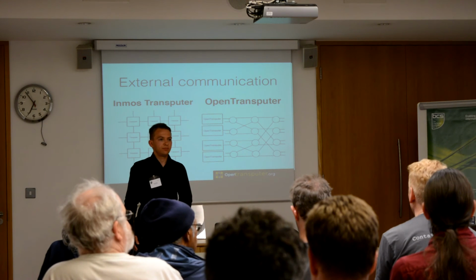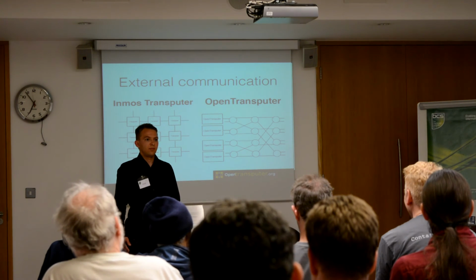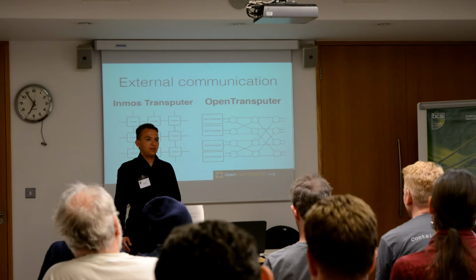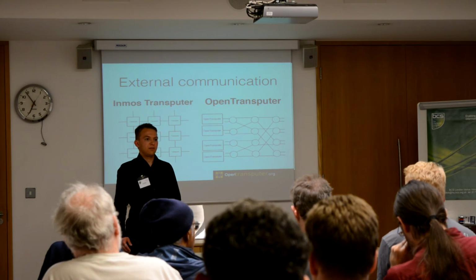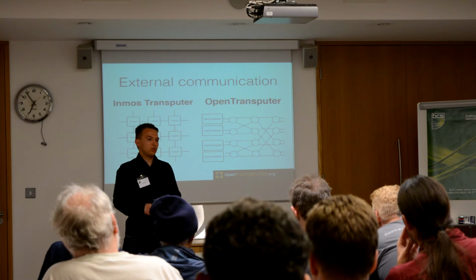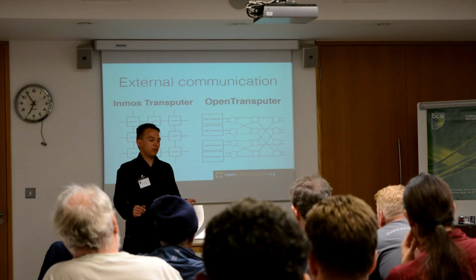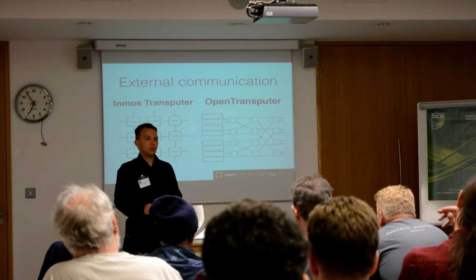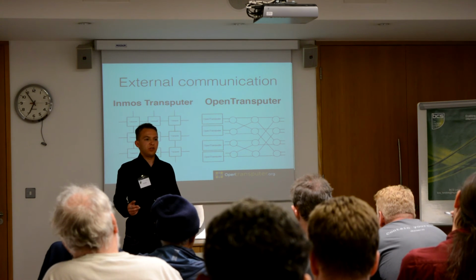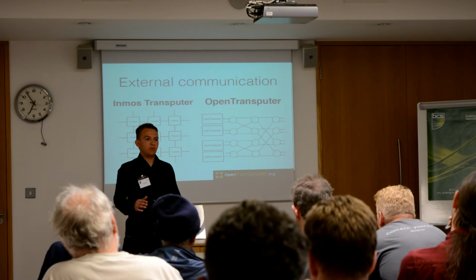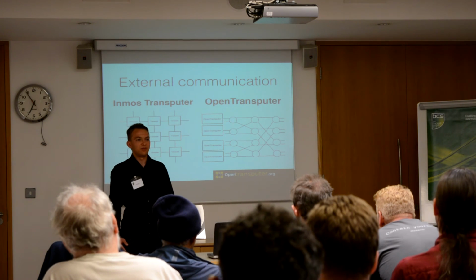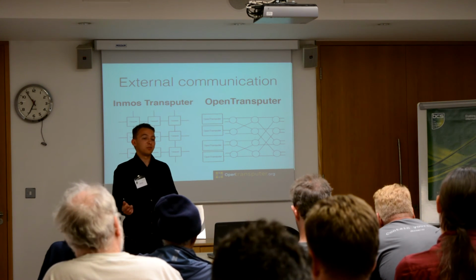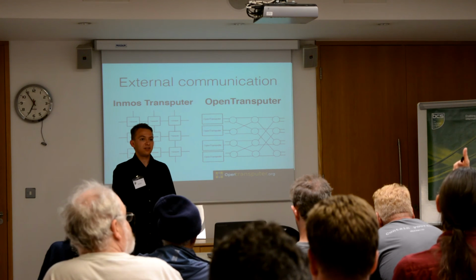What sort of dev board FPGA-wise are we going to need when you open source the HDL? Is it going to be a very specific board, or do you think it's going to be able to run on over anything? So currently we use Vivado and a set board FPGA, as I said. So the Verilog code will probably just work in a simulator without much fiddling. To actually get it to work on a specific FPGA, I think there's always some custom stuff that you might have to do. Hopefully we have some sort of community that can help out with that.